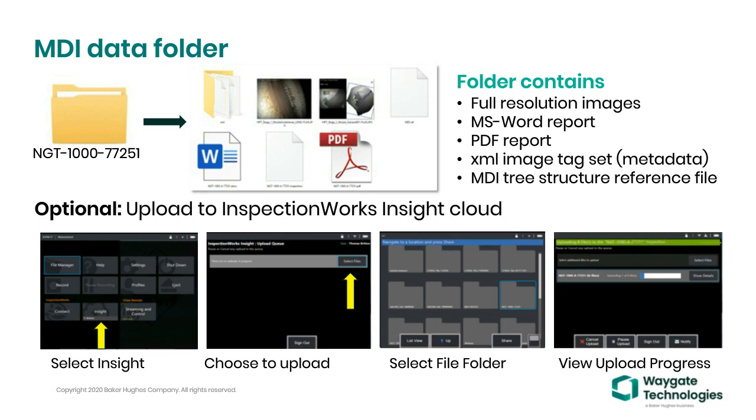The bottom half of this slide shows the steps that are needed to easily upload this MDI folder or in fact any data file to the Waygate Technologies InspectionWorks Insight AWS Cloud. The steps are pretty simple. Just select Insight, enter your username and password, select a file or folder to be uploaded, and then begin the upload.